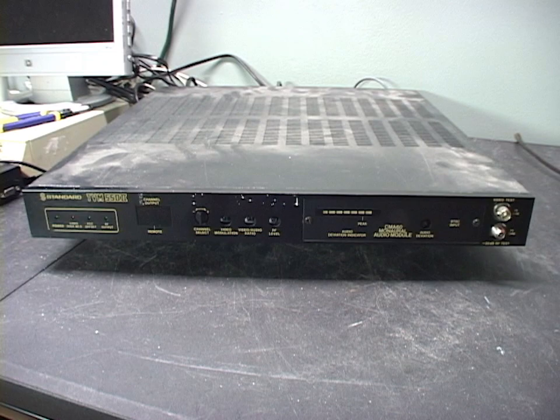So you're a TV station and your channel gets to be carried on the cable network. You are going to be given one of these modulators by the cable company, and a direct cable line is going to be run between your TV station and the cable head end. And the job of this modulator is to take a composite video feed from your TV station and modulate it onto some RF channel chosen by the cable company's engineer and sent out over that dedicated line to the cable head end.